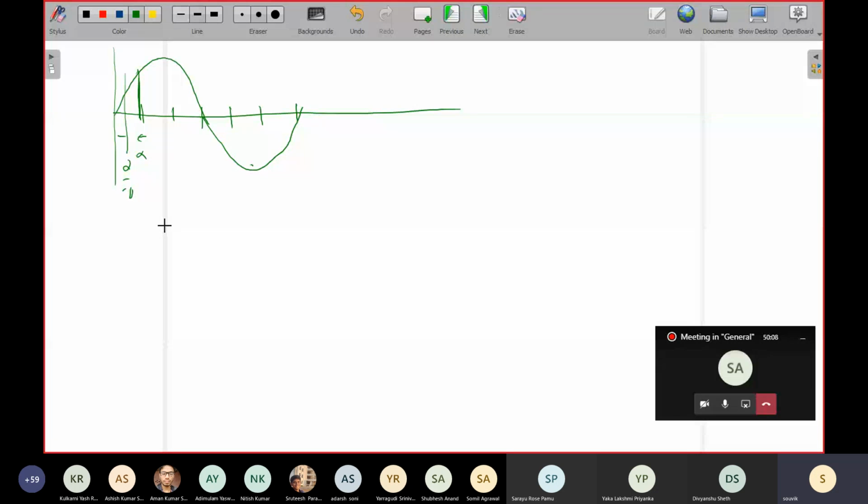Earlier, in the case of single phase, I talked about a modulation scheme called the cosine modulation. So let us say we want to develop a cosine modulation scheme for this. We are now concentrating on thyristor 1, TH1, and for that I want a cosine modulator. The cosine function has its zero at 30 degrees. This gap is 30 degrees, so the cosine should have its peak value there. That is how it has to be constructed.